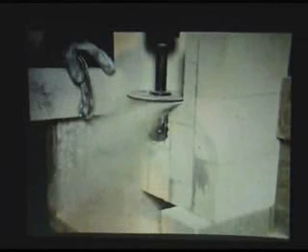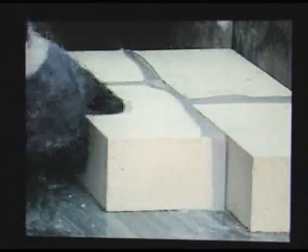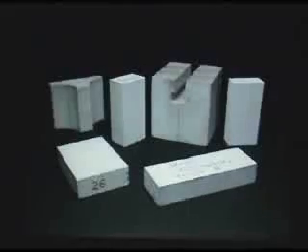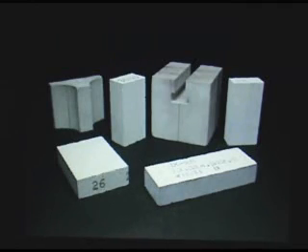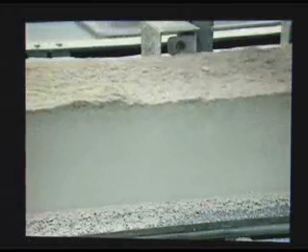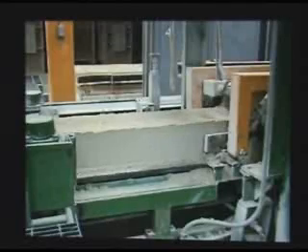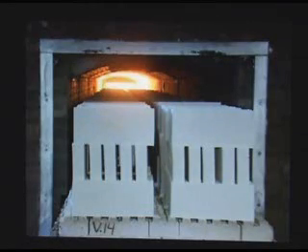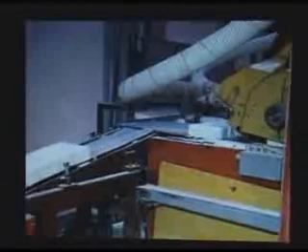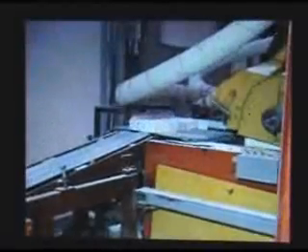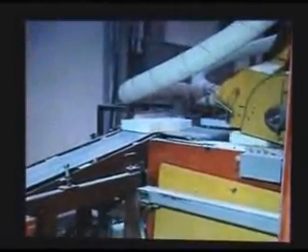The IFB can be custom ground or ordered in mill-cut shapes to meet specific customer requirements. The higher temperature brick grades TC26 through GM30 are made by a continuous slab forming process. A ceramic bond is formed during high temperature firing, and they are cut to final brick size. This process produces high temperature insulating firebrick that are both dimensionally accurate and thermally stable at temperatures up to 3,000 degrees Fahrenheit.